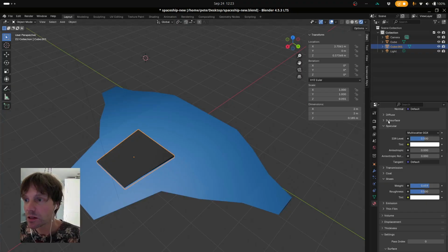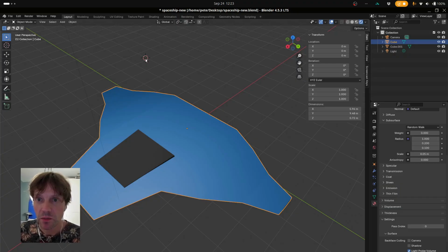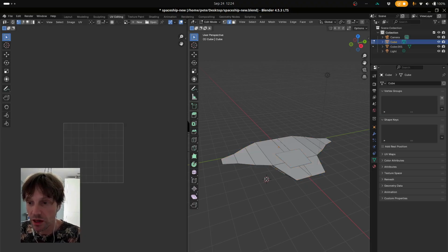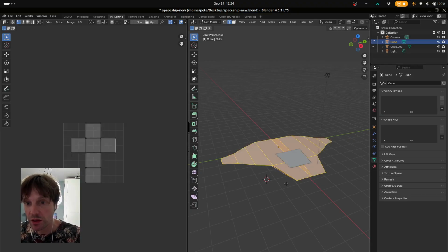So how would I add my custom textures here? Well, I can select this part, and we're going to go into UV editing. In UV editing on the top you see a left and right. So right now the entire thing is in edit mode, everything is selected, so all the surfaces are selected. Or you hit A if it's not selected. Let's say nothing is selected, you won't see the actual flat representation for a potential texture on the left. So we have to go on the right and hit A to make sure everything is selected.